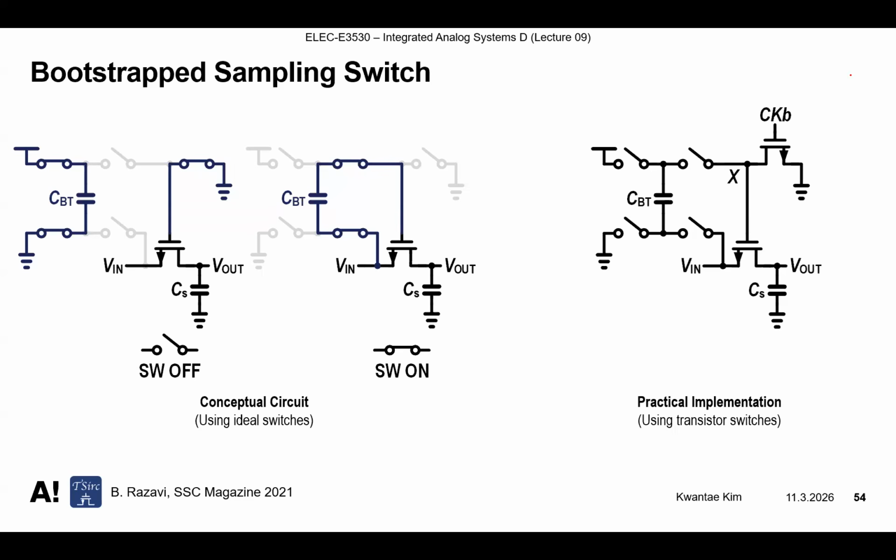And the next thing, we can realize this switch. For this PMOS switch, there is some consideration required. If we just connect it here, the body is assumed to be ground without any notation. And I specifically connected the body voltage of PMOS to this node.